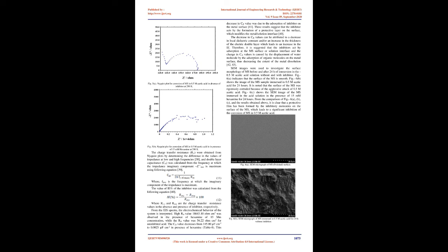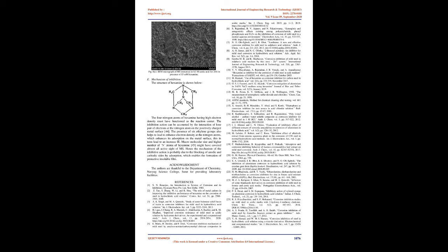D. Electrochemical measurement. Various electrochemical parameters such as corrosion potential, Ecorr, corrosion current density, Icorr, and the values of the Tafel parameters, βa and βc, derived from the potentiodynamic polarization measurements, were shown in Table 7. The percentage IE can be calculated by using the following equation 36, where Icorr U and Icorr I are the corrosion current density for uninhibited and inhibited system respectively.